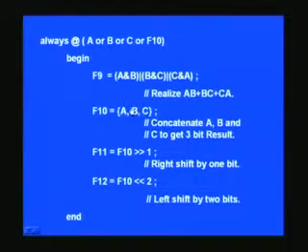You can insert anywhere, or instead you can put any other signals which are already available here. We have also seen shift registers, right shift by 1 bit here and 2 bits here. It is as simple as one statement, right? After right shifting by 1 bit, it doesn't affect F10 itself, which is the source. You can make it affect some other signal, say in this case I have named it F11, and that is the beauty of this statement. So is the case with left shift.